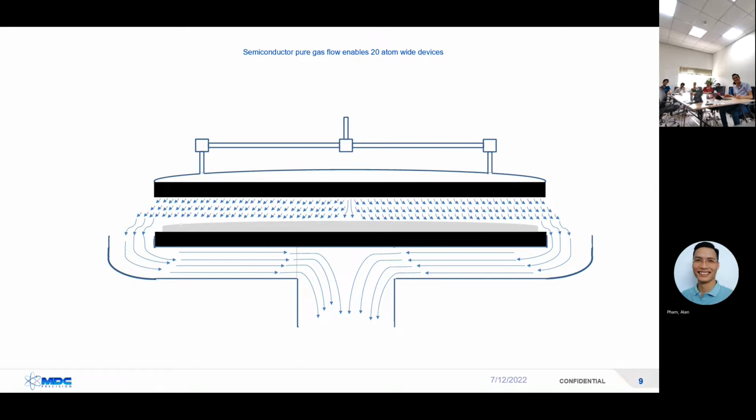If in one of these areas the gas flow is not quite right, so now there's a silicon dioxide that just says, you know what, I don't want to deal with that fluorine guy out there. So he stays. Now I'm 1/20th, I'm 5% error versus the next one, and the transistor doesn't work. So we feed the chamber kind of like this. If we have a weld imperfection out here or contamination out here versus this side, more gas will flow to this side because it's less restricted. You'll have an imbalance in here, and now the transistors on this side will be different than this side. That's how important it is.